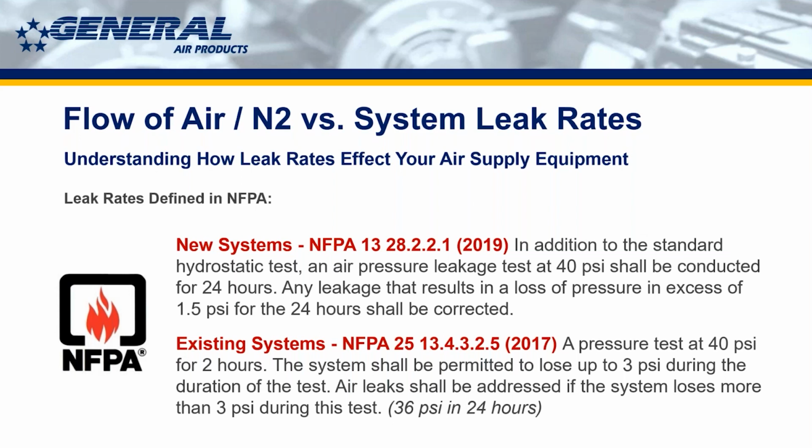But I would always recommend, and the problem is that it costs more to size by the existing system leak rate, but it's going to give you a larger generator that's going to have a higher cost, but it's going to size the unit properly. And that's really what you have to look at in terms of what's best for the system when you're using the nitrogen generator.